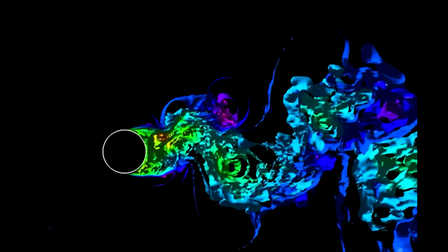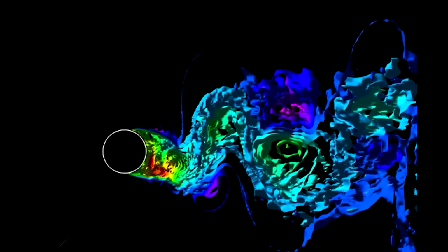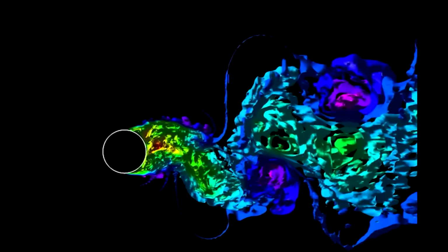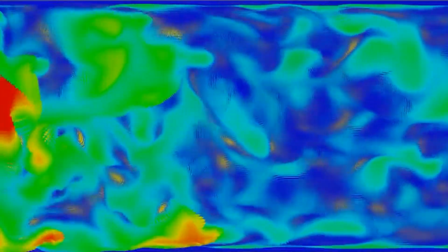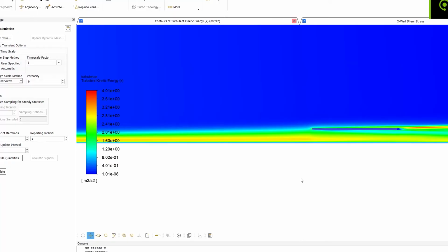So firstly, I want to quickly go over what large eddy breakup, or LEBU, actually is. It is a relatively niche subject that many people may not have knowledge of. In a turbulent regime, large eddies are vortices where fluid tends to swirl behind an object that interrupts flow. In these eddies, the fluid can be reversed and flow upstream, creating a vortex. These large eddies account for large amounts of turbulent energy present in flow. Large eddy breakup aims to interrupt these vortices by placing a device within the boundary layer of a wall, effectively reducing the drag on the wall.